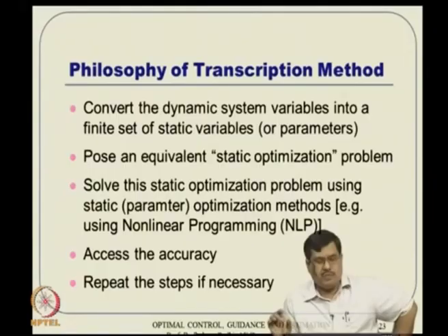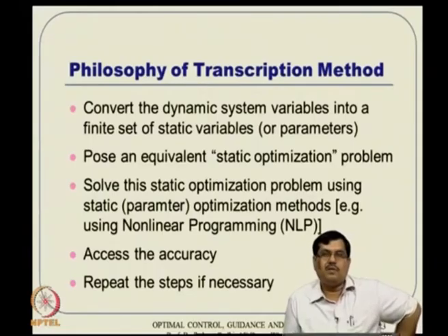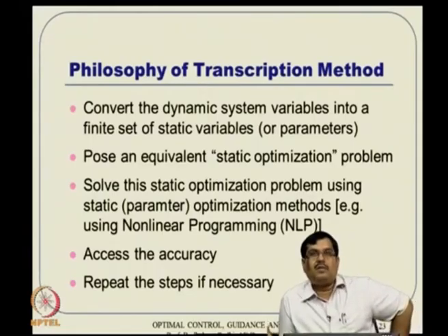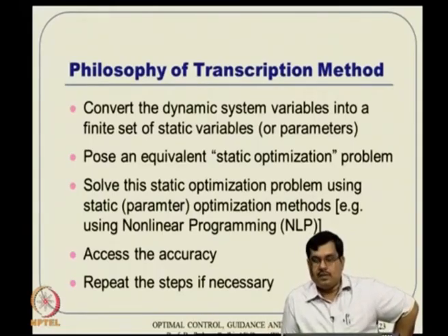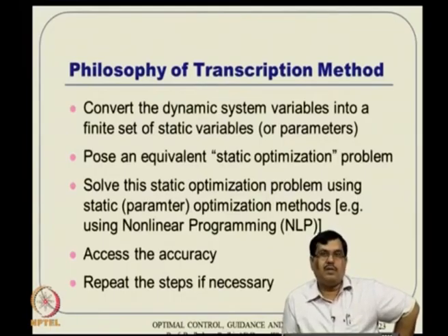So if you see that for better accuracy, you need a lot of grid points actually. And then if you have a lot of grid points, then essentially it leads to a high dimensional optimization problem, which has its own difficulties actually. Okay. So these kinds of issues come into focus actually. Then people have used something like sparse algebra, or start with something like grid refinement, and a variety of ideas there, where you start with a coarse grid, and then once you get a converged solution for that, refine the grids and again start solving it. And things like that. That is grid refinement.